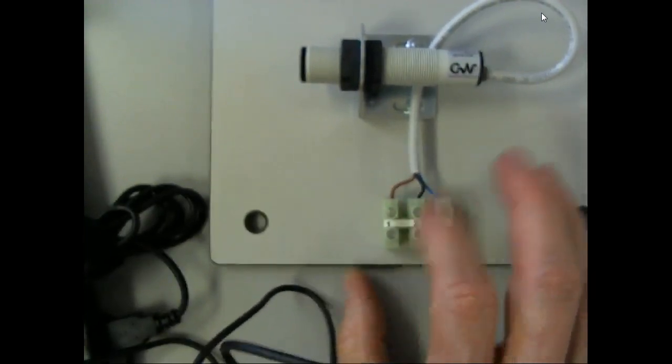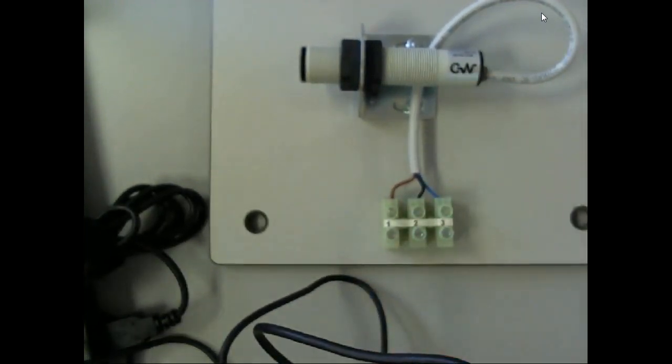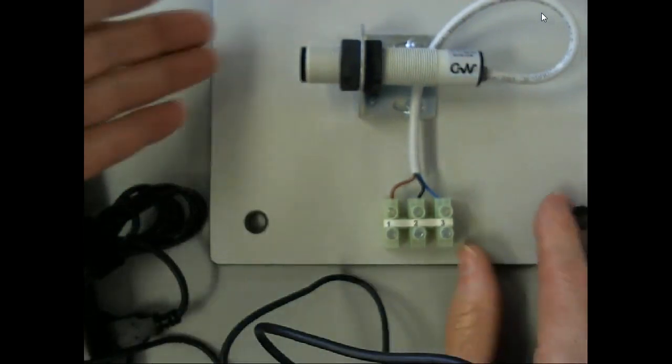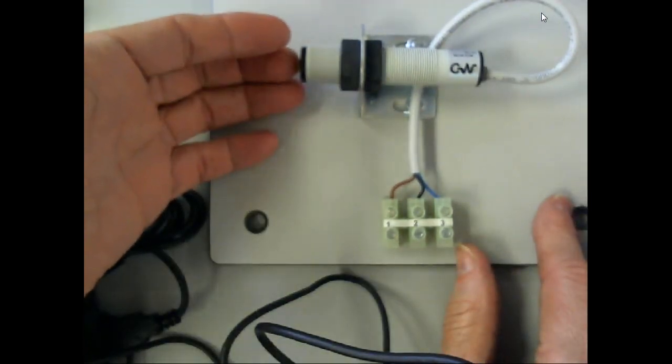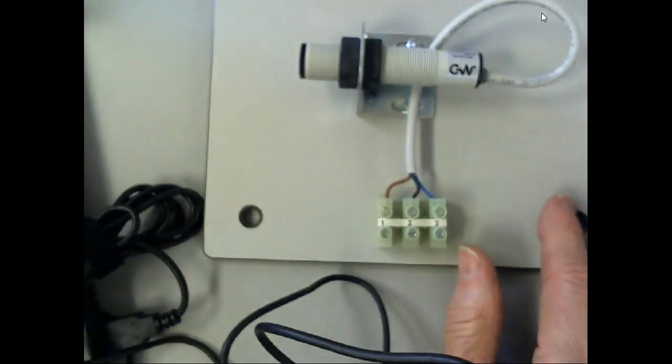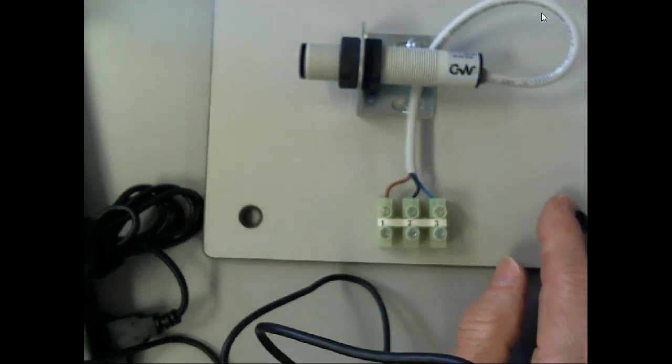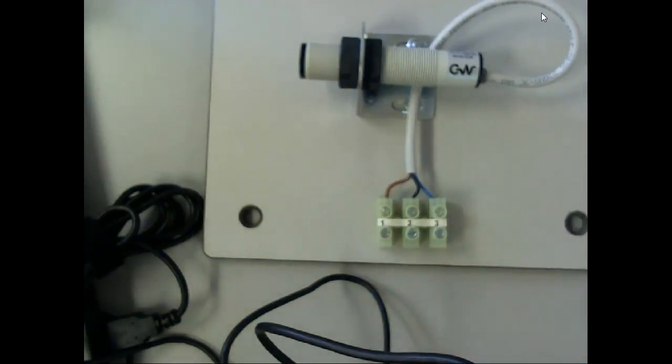This is a 3-wire sensor, so this is going to simulate a normally open switch. But there's no moving parts. So when this guy sees light of a certain intensity, what is it going to do? It's going to simulate closing a contact. And when it doesn't see enough light, it opens the contact. But there is no physical contact. We have these guys all over the place. Some examples.